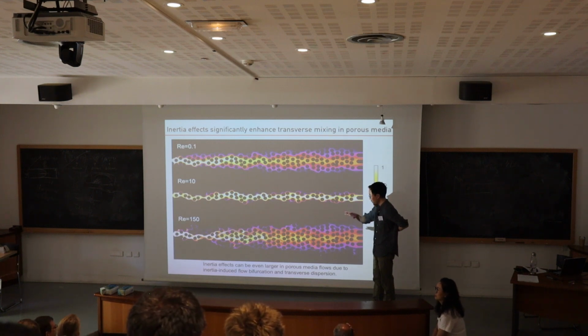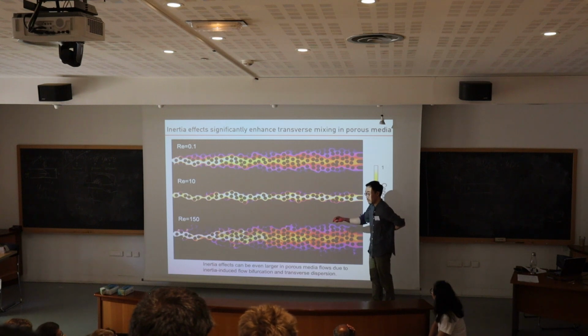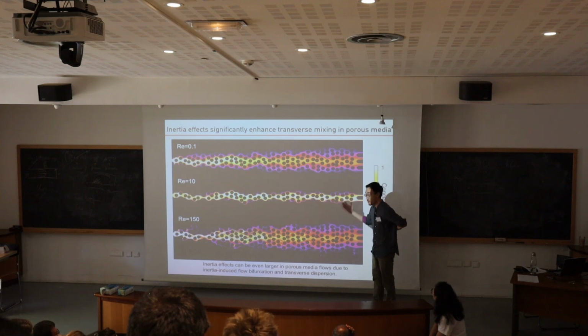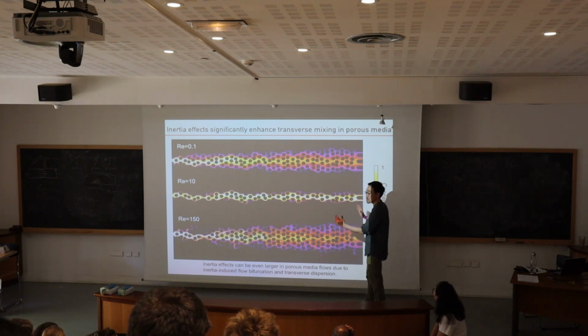Yeah, I mean, thanks for asking this question because it's essential. And I'm convinced that this is inertial laminar without any turbulence because of a few reasons. First, you can run direct numerical simulation. Flow field converges to steady state. So that's the first thing. Experimentally, you can just see the concentration field, zero fluctuation. How can it be turbulence?